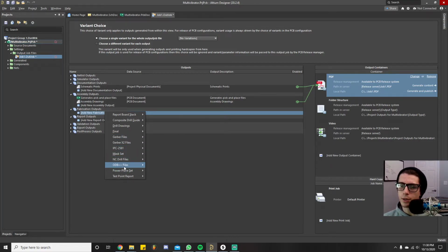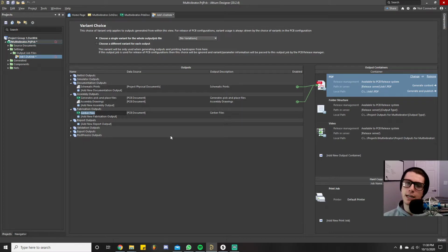I know with ODB++ you can also do that, because I remember I've actually gotten this manufactured. I'll talk about this at the end, but I remember when I talked to a manufacturing engineer, they were asking me for ODB++ because it had some information in it. So, I hope that makes sense. So the Gerbers are just chock full of information. So it says Gerber files, NC drill files. That's one thing, I guess, the reason for learning all these files is to figure out which ones have the information you need. Because they don't all have the information packaged in the same way.